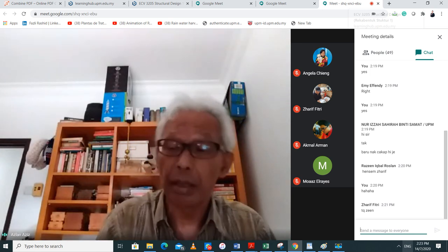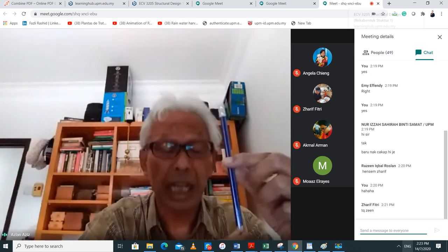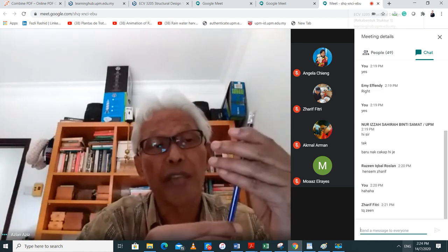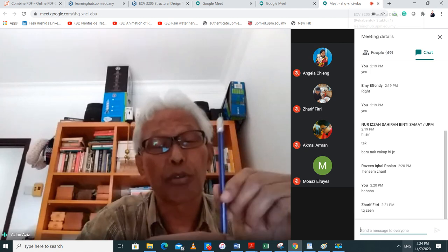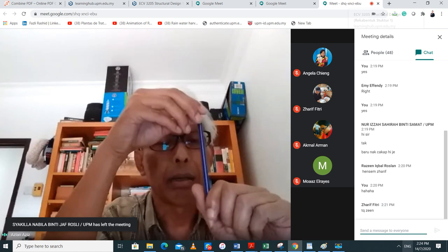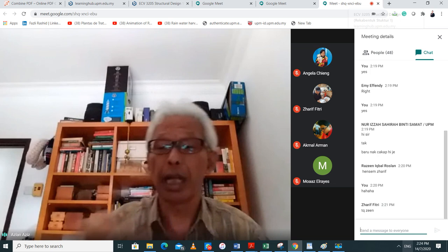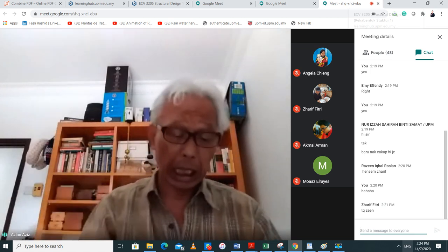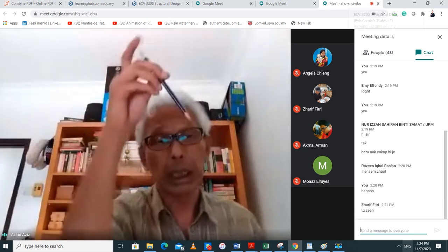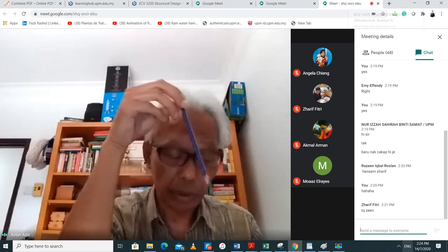If I have a penetrometer, I have F sub C and Q sub C. F sub C is the shaft skin friction of the penetrometer, where the subscript C is just the symbol for the cone, and Q sub C is the tip of the cone. Those are the two that give you the ultimate bearing capacity when you penetrate the penetrometer into the sand.